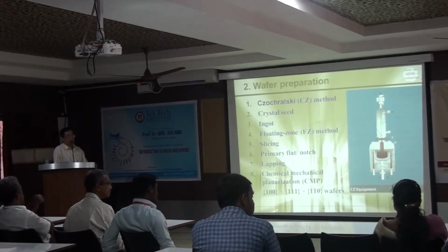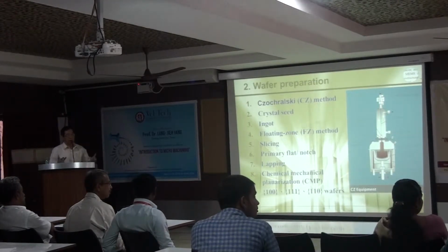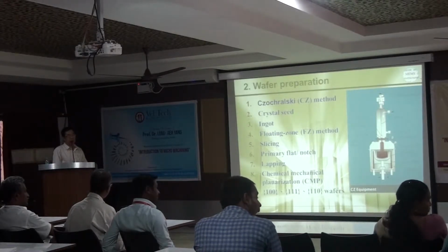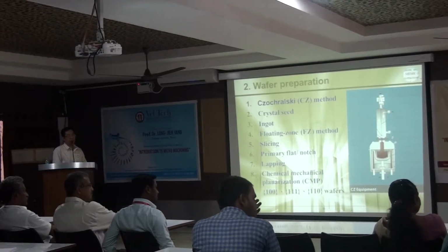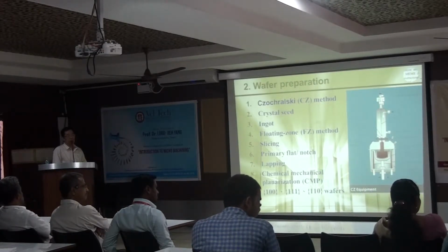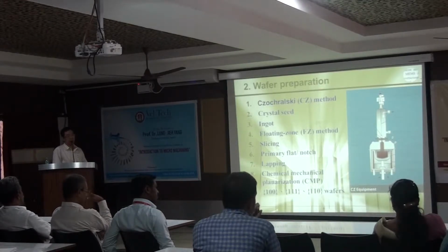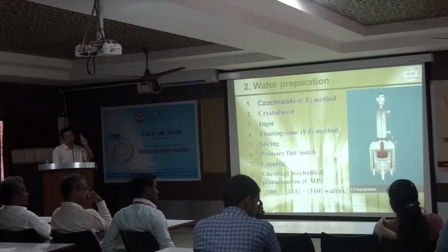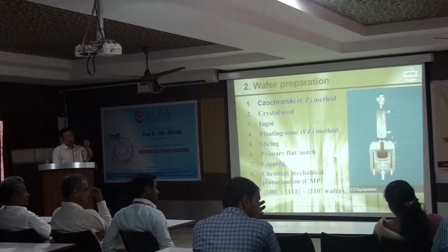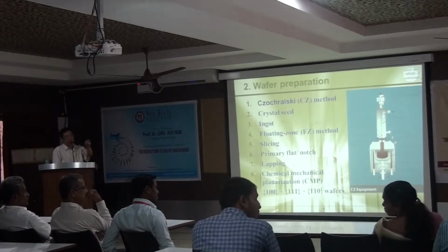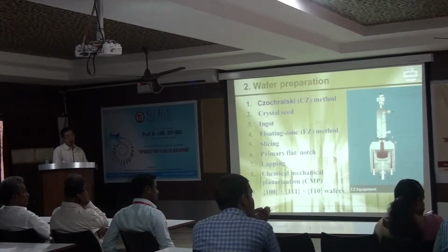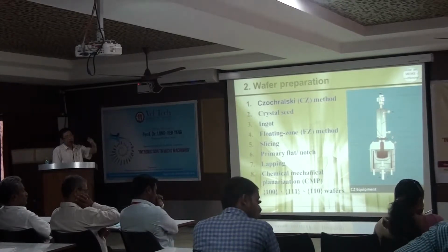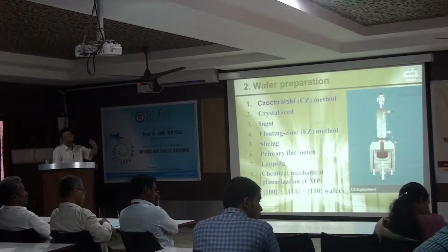But for 8-inch and 12-inch wafers, the size is now too big, so we abandon the primary flat. We only leave a little place, which we call a notch. It is only a little bit of machining, a small part of the cut. This notch is exactly at the same position as the tangent direction of the primary flat.